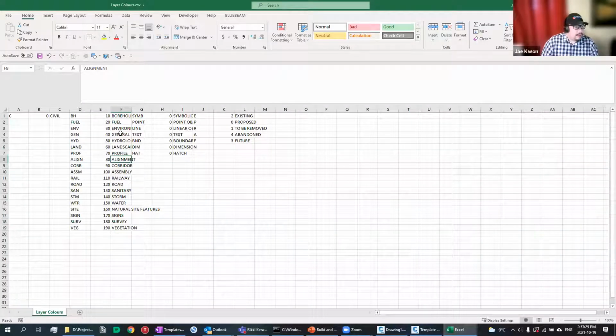So that's basically what I have set up. The base colors are determined by the category. The subcategory, I'm just not going to modify the color at all, so add 0. Same with the discipline, just add 0. Don't modify it by discipline or subcategory. Just set it by the category and then have the status determine what shade of that color we go with, what brightness. So that's the setup that I'm going with.